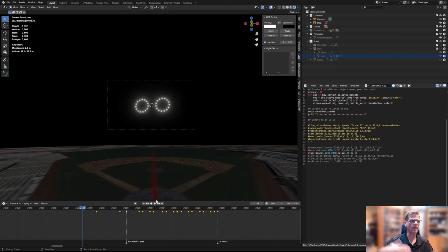We went in and out of object and edit mode, which is super duper important. How to pair the vertices to the drone so they actually work when you add it to the formation. And then the really important thing to start learning as you get into more complex designs is the parenting and rotation about the axes.